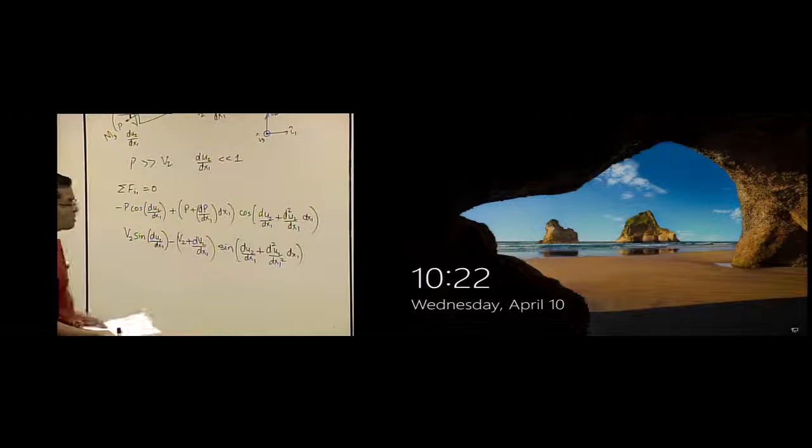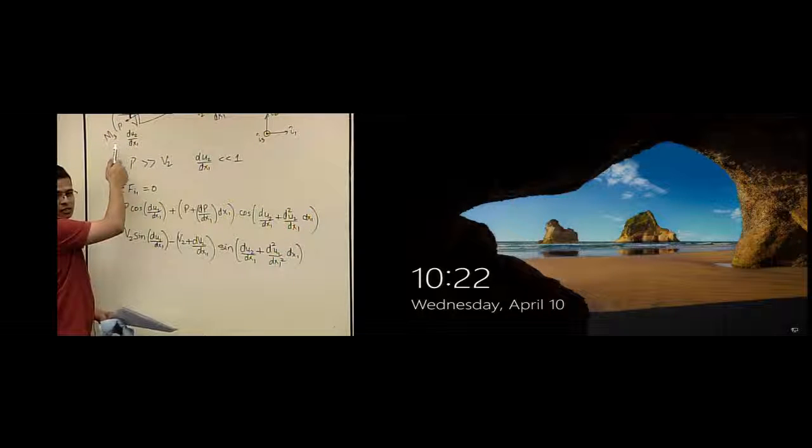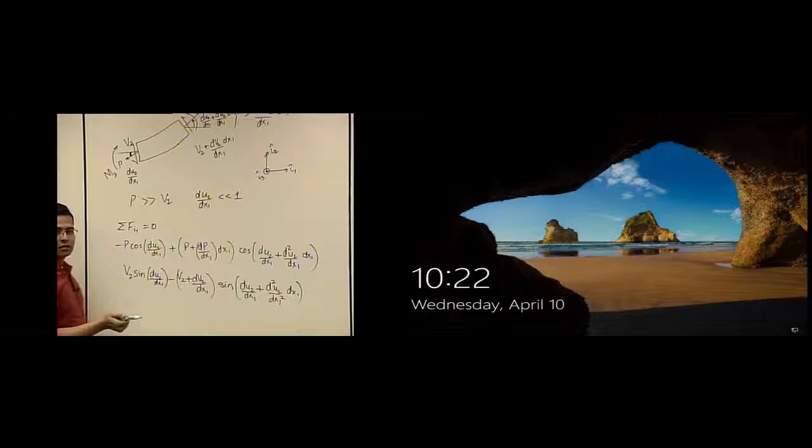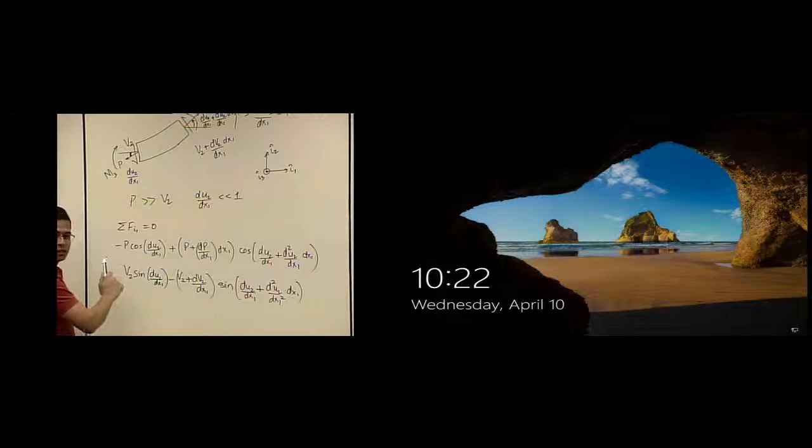Why was it not this complicated when we did it before? So this axial load is an additional term here that's causing this entire term to appear. But we did have axial load before. Yes, but what we say is if the axial load is applied at the centroid, the problems are decoupled. The axial problem and the bending problem are decoupled.